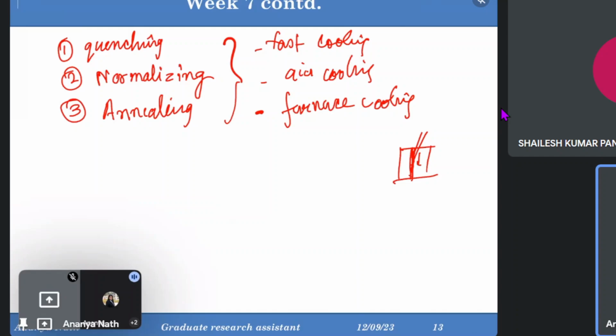As they solidify, grains will be formed anyhow. The grains will be smaller, because it's not that the whole liquid metal solidifies as only one grain. A grain is nothing but a single orientation: the lattices oriented in a particular direction form a grain. The lattices inside aluminium always follow the FCC crystal structure, but the orientation of the FCC crystals is not the same throughout the metal. They are oriented in different directions, and if you freeze the material then, they will solidify as small grains.